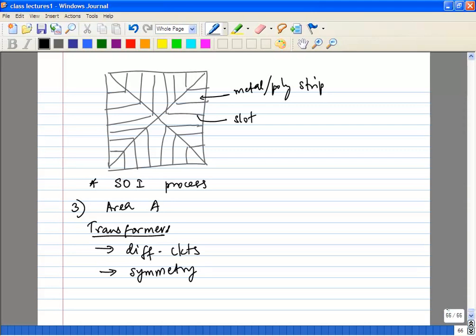Okay. So let's say you are going to design. What else do you need? You want your mutual inductance to be as high as possible. In other words, your coupling factor, right? Coupling factor is usually K. You want to increase it as much as possible. Okay. And there may be certain cases where you might be interested in a specific K. There may be certain cases where for proper operation of a circuit, you want to have, let's say, K equals 0.8, a coupling factor of 0.8.